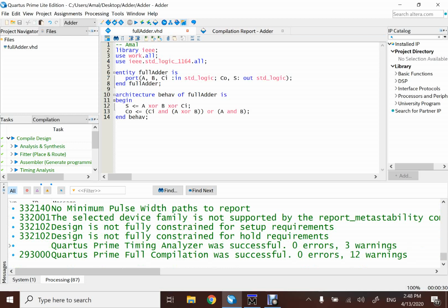especially if you intend on copying, for example, the library part of the code. So if it has an error, you're going to have errors everywhere in each of your files. Now, if I copy the library part of the code, I'll make sure that at least these 3 lines are correct for the rest of my project files. Now, this will complete the behavioral modeling of the full adder. We'll move on to how to simulate it later on.